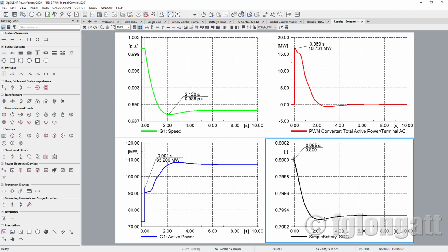but in this very specific point, what is happening here is that the battery starts to take power from the grid, and that is not quite good. Okay, during an under frequency event, we don't want the battery taking energy from the grid.